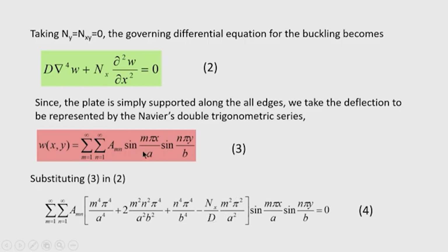The same procedure can be applied when there is say load in the y direction. Okay. Here the in plane force is in the x direction, but in some problems the in plane forces are in the y direction, or there is a combination of in plane forces in x and y direction as well as membrane shear forces. Then also this function can be substituted in the original differential equation, and we can get a relation like that.